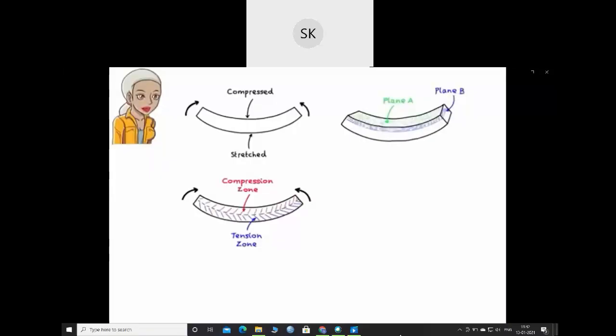Similarly, the conjugate beam has the same length as the real beam, and the bottom part of the beam always undergoes tension, and its fibers stretch. The outer fibers are stretched more than the inner ones. But the supports for the conjugate beam, however, could be different than those in the real beam.